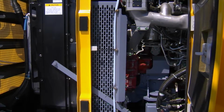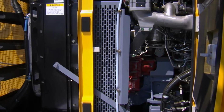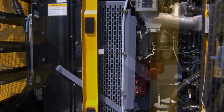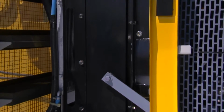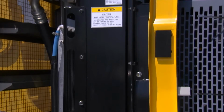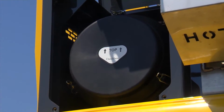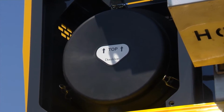Next, we have the engine coolant radiator, engine fuel cooler, engine air after cooler, and the hydraulic oil cooler. We have removable side panels to assist in the external cleaning of these coolers. Above the coolers, we have the main engine air filter and the access panel to add water and engine oil as required.